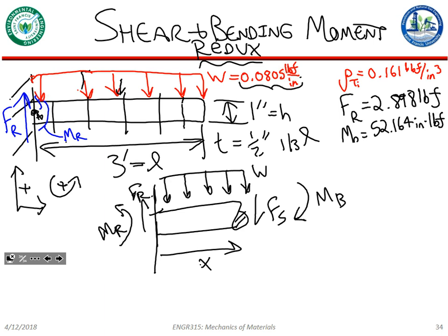You might say that the load is continuous along the length. Previously, we had to make a new free body diagram every time we crossed a new load. Here, it's a continuous load, so we can make an expression for how the force pressing down varies with X. Because this is a linear density, whatever our X is, multiply that by W to get the force pressing down.